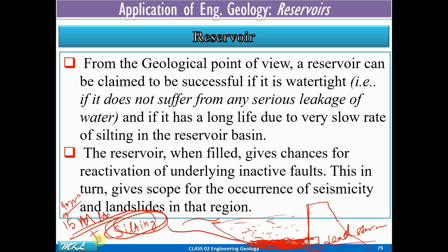Then you have to consider the siltation rate, and you see that the silting over 40 years will be, suppose, 6 million liters. So what you will be doing is making a dead storage plus this 15. So you will be making a total of 21 volume units for that reservoir, because 6 will go into dead storage anyway.